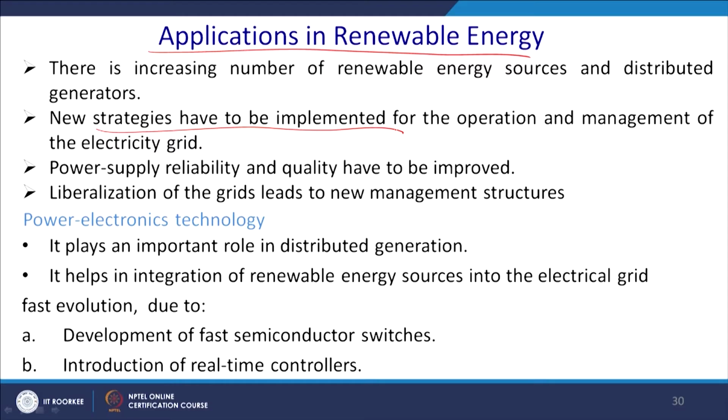Nowadays, except I believe the northeast, the whole of India is connected by a single grid, and thus it has a huge inertia, but our solar inverters have almost zero inertia, or very low inertia compared to the alternator. So once you incorporate a very low inertia system with a high inertia system, we require grid parity and all those things.